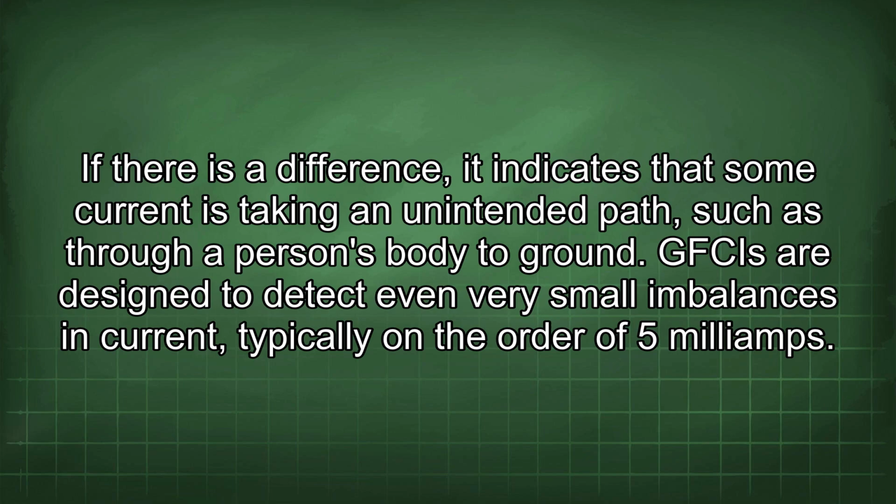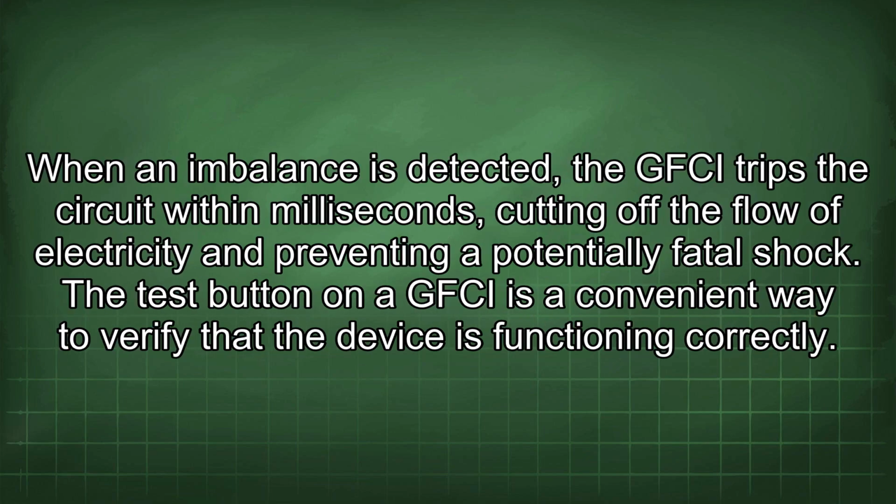GFCIs are designed to detect even very small imbalances in current, typically on the order of 5 milliamps. When an imbalance is detected, the GFCI trips the circuit within milliseconds, cutting off the flow of electricity and preventing a potentially fatal shock.